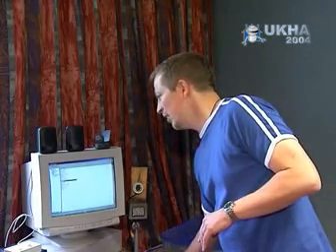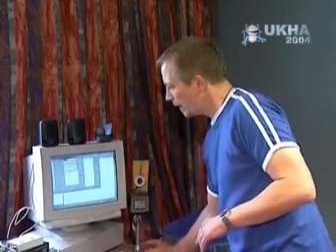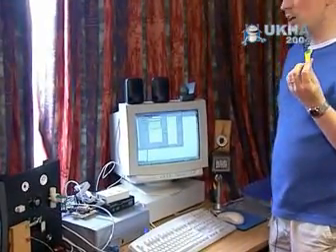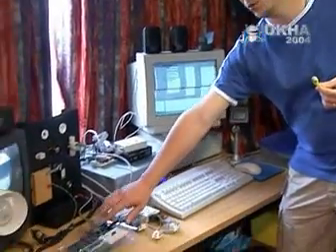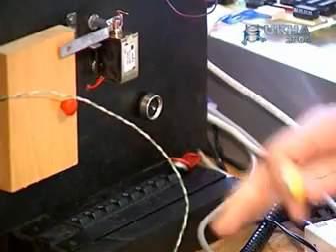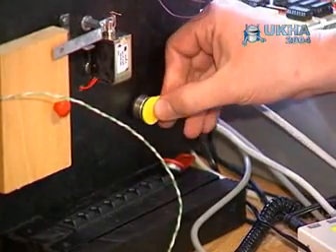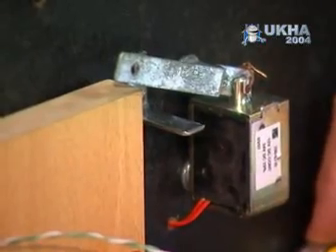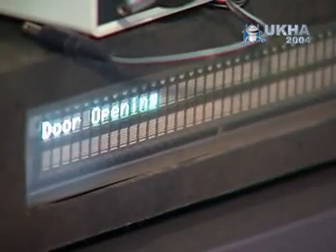One of the things we've got set up is, for instance, an I button at the door. When a particular I button, one of these yellow one-wire devices, gets triggered on the development board here, which is just a PIC development board, that will trigger the Home Vision unit to open the door solenoid unit. This camera here will capture a picture of the person opening the door. It will speak "opening the door", and also we'll get a display message up on our unit.